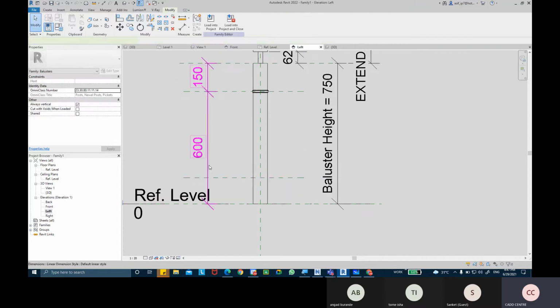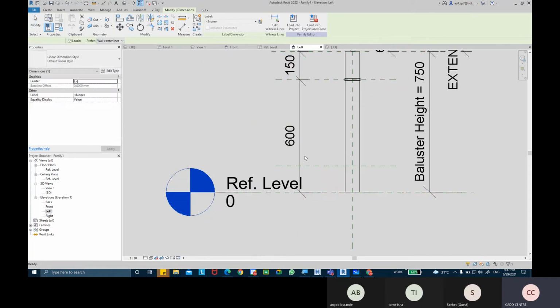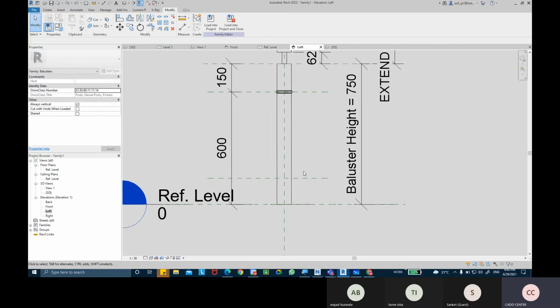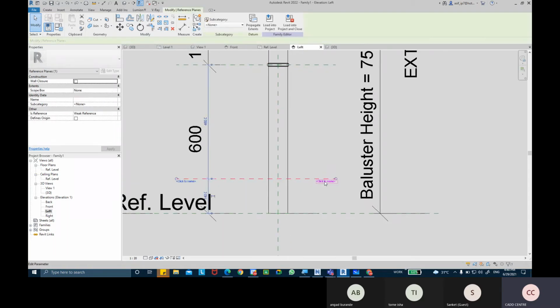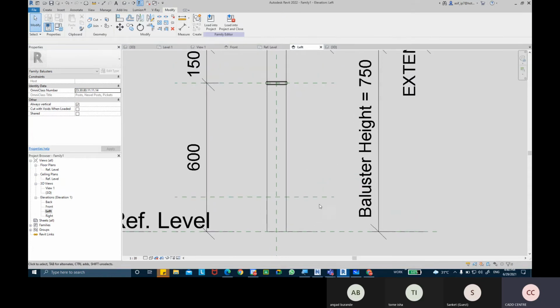Right, and take this line, put it back level. Later on, you can give the dimensions. I'll select that reference plane and name it bottom molding pattern plane. So we can easily pick that plane through that name, and we can create a sweep object on it.